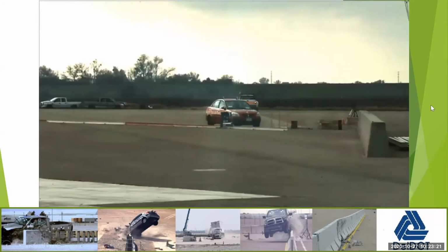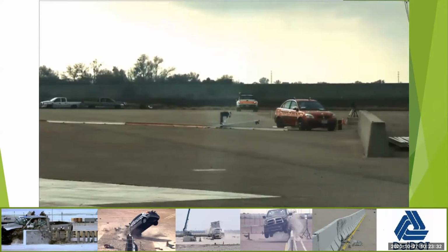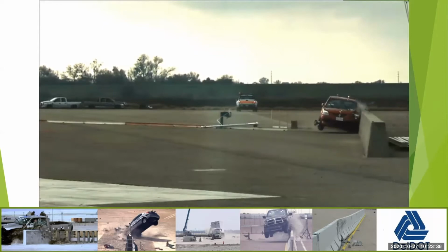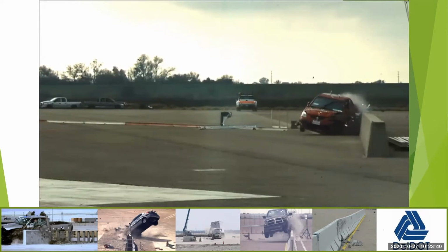All right, so that video explained what rollovers are. And so rollovers are very severe. So the single slope, and this is a small car test for a Caltrans single slope barrier. Just notice how clean this car comes off this wall. So you get a little bit of uplift, but not nearly the instability that you saw with the safety shape.